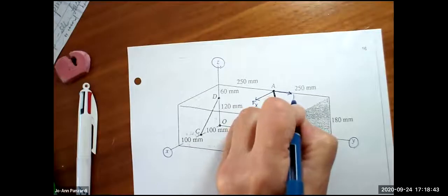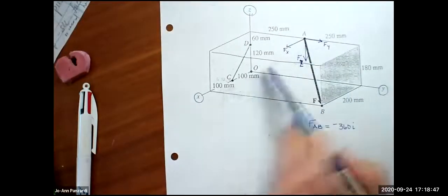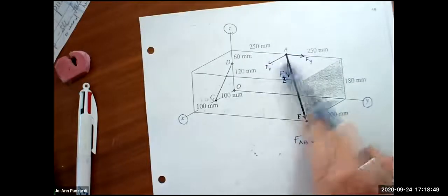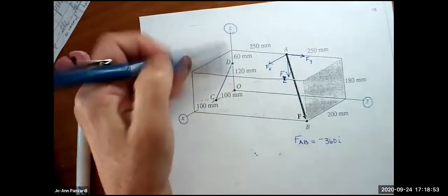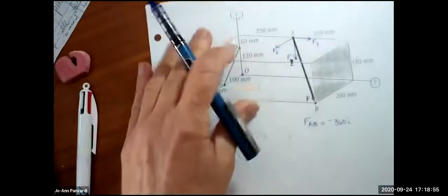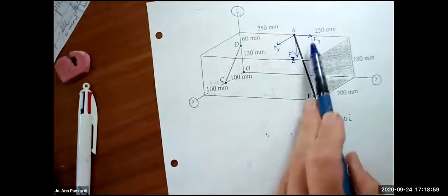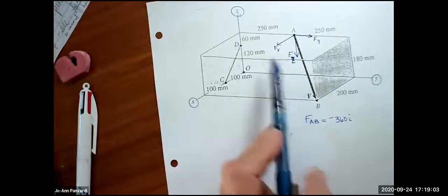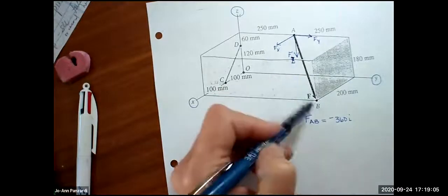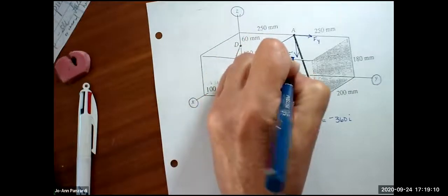And the reason why I took a long time to do this is I want to show you that you're looking at lines being parallel. X is parallel to X, Y is parallel to Y, Z is parallel to Z. Make sure you draw it that way. So you can see that FX is positive, FY is positive, and FZ is negative, okay? And I want to call F going from A to B, so I really should have put AB next to all these.